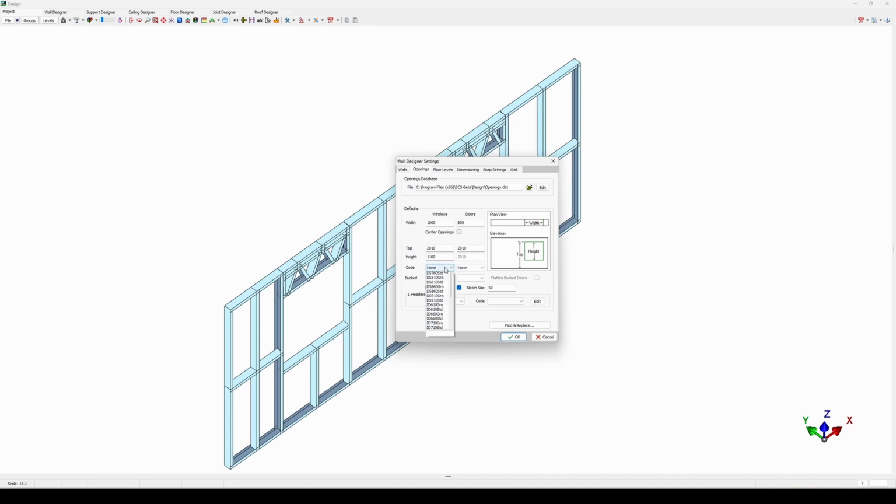When you get to the code drop down right there, it is basically recalling the saved data that you've inserted in your database. On the backing option, this is generally a timber finishing being used on the inside of your framing and outside of your window itself. You do have code available there to use for the type of backing that you'll insert. The next option you'll have is to click on or off for the notching of your doors.